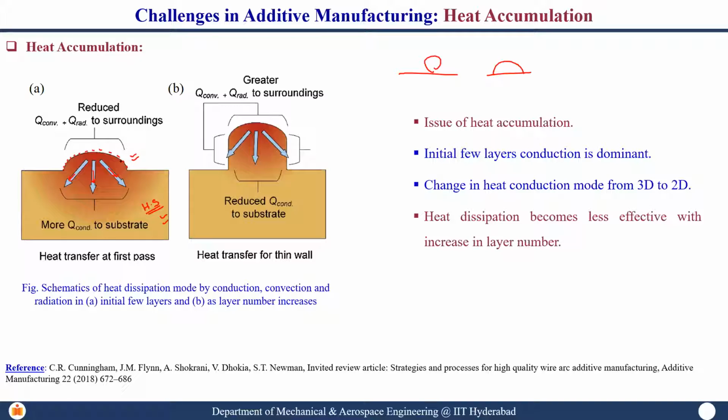Good, very good. Then you start depositing layers one after the other. As you keep moving in the z direction, the distance of the deposited bead from your heat sink, let us not call it the substrate, the distance from the heat sink increases.